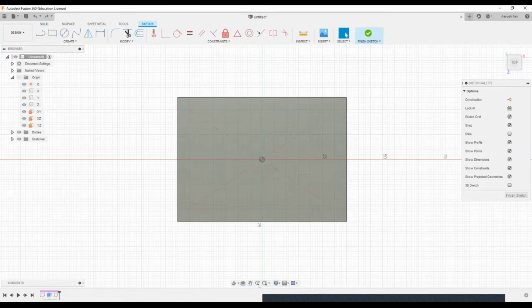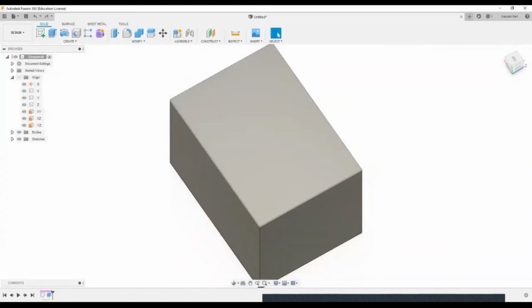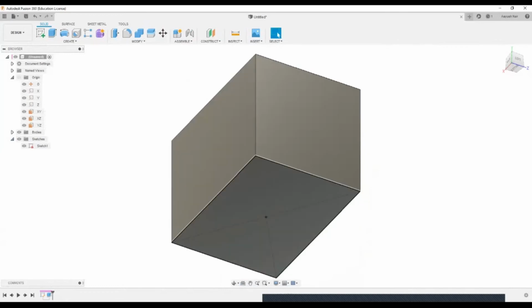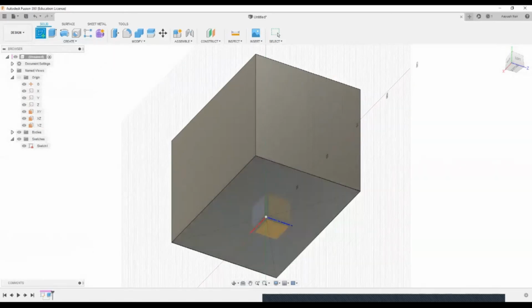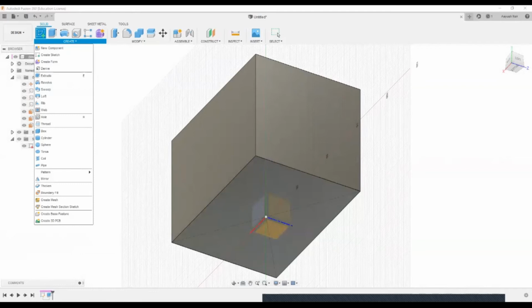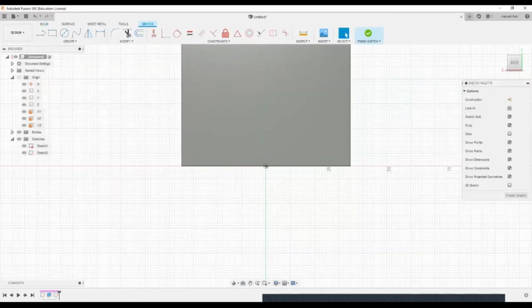Okay, so like that also we can do. Otherwise, I would like to do it in some different manner. I'll show you how. See, here are the sketches available that we have drawn previously, right? I will select the sketch and I will just enable the sketch. Right now it's disabled, you can see here. I will enable it. I will go down and see here I've got my sketch. Now what I'll do is I will go to create sketch, and I will select the key O, which means offset.